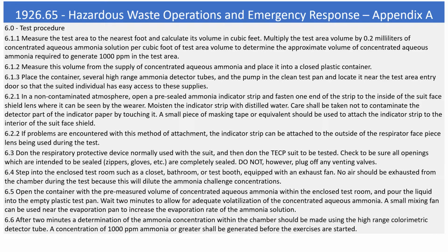6.4. Step into the enclosed test room such as a closet, bathroom, or test booth, equipped with an exhaust fan. No air should be exhausted from the chamber during the test because this will dilute the ammonia challenge concentrations.